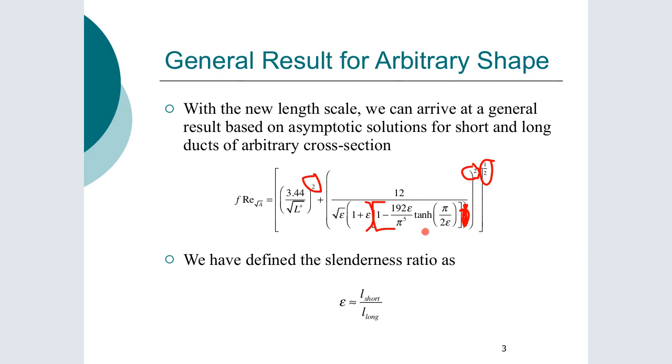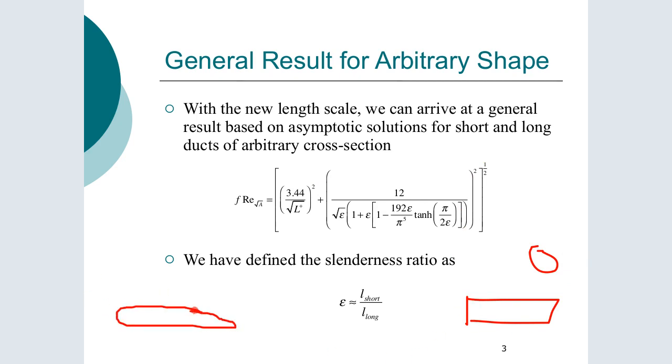All right, so what this gives us is a general expression for calculating the friction factor for any arbitrarily shaped channel. Again, why is that useful? Because in microfluidics, although we might like a rectangular cross section or a circular one, we get something wonky like this, or you'll have curvature, with more elliptical type shapes and stuff like that. And this is a way of calculating it.